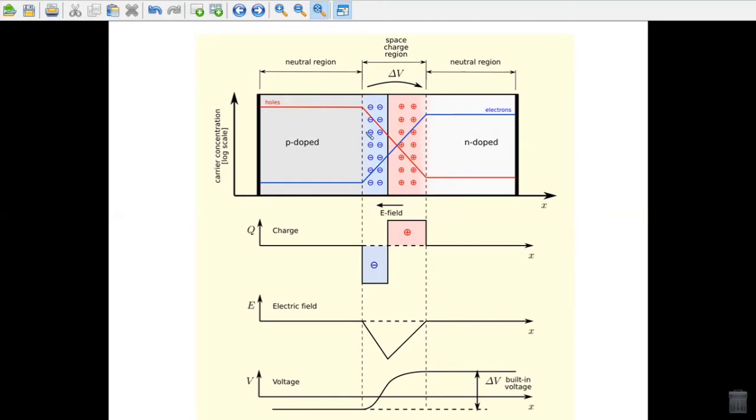The area where this process occurs is called the depletion region or depletion layer, as these ionized areas are stripped of charge carriers and therefore unable to carry current with the band structure that already exists. This PN junction is incredibly important in solid state electronics.